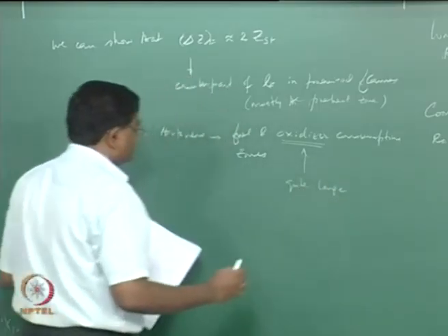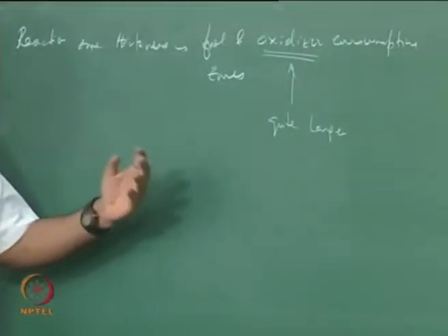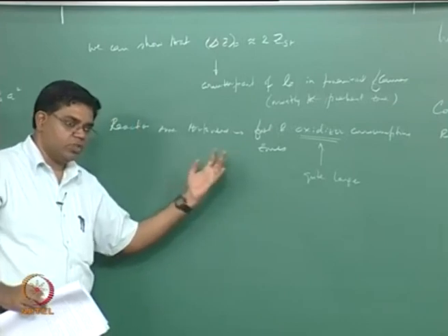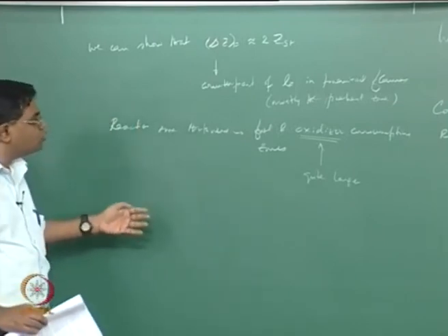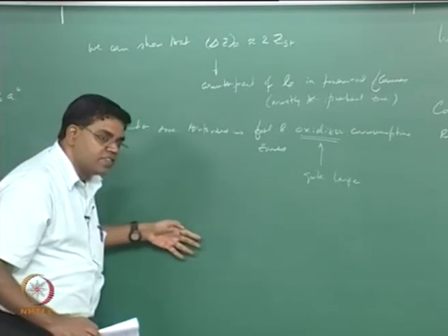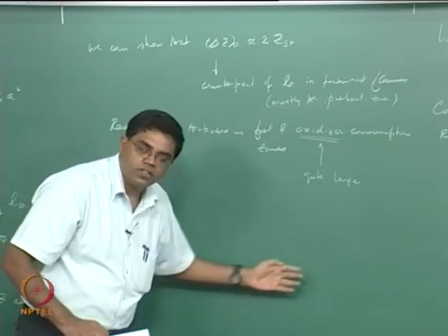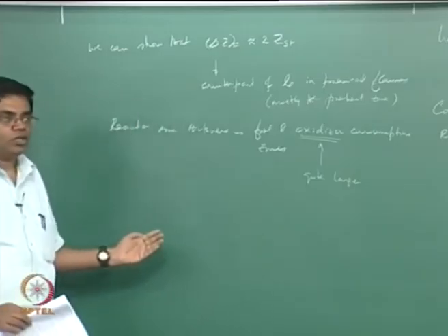That is what we are saying: if you now do actual detailed chemistry for, let's say, methane air flames or something, what you should find is the oxidizer significantly leaks out of the reaction zone to a farther distance outside, into the fuel region.